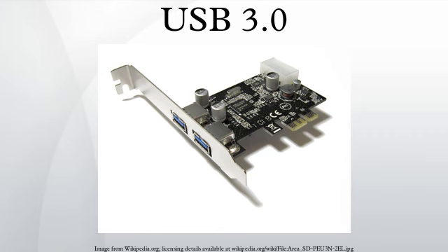Type B plugs in USB 3.0 are somewhat larger. Therefore, a USB 3.0 Type B plug cannot enter a USB 2.0 or earlier Type B receptacle. Accordingly, normal USB 3.0 Type B plugs cannot be inserted into normal USB 2.0 Type B receptacles found on peripheral devices. A receptacle for eSATA is designed to accept USB Type A plugs from USB 2.0 and USB 3.0.